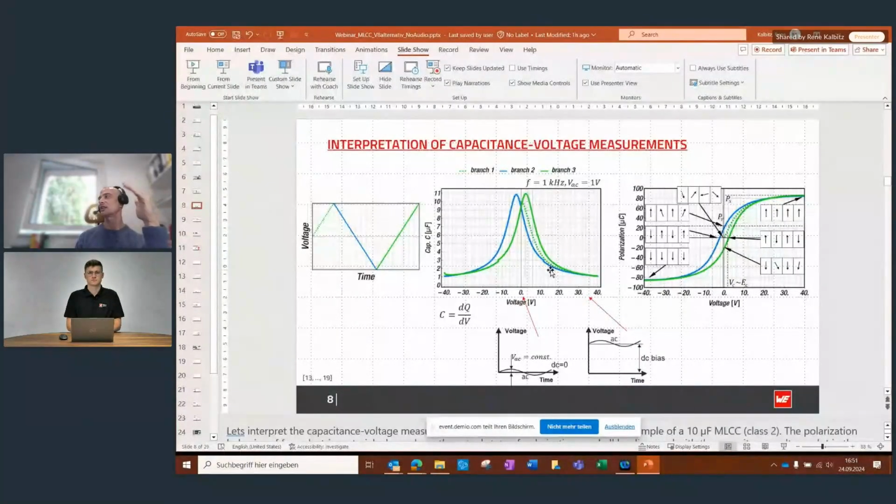But if you are just interested in the effect at an applied voltage, you don't need to care about the memory effect so much. All you need to know is, I see a decline and this is it. But you have to remember, depending on the application, that once you remove the voltage, the polarization state is maintained, and that indeed influences the capacitance, may decrease the capacitance. I hope that answers the question.